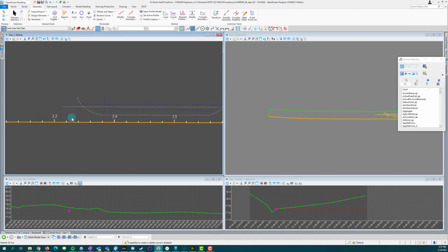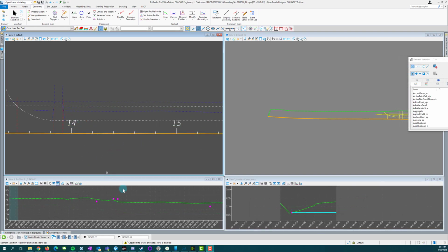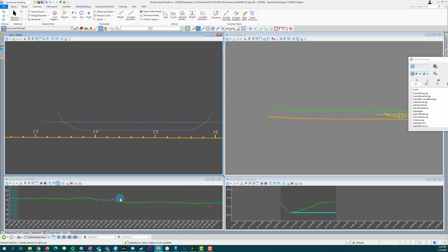So what I'm going to do real quick is finish up the rest of these other 4, and then we'll be right back. Okay, so now I have my 4 points projected back to my center line. The other thing I want to kind of look at is where is this back of sidewalk profile landing with respect to the right-of-way line and the edge of pavement.